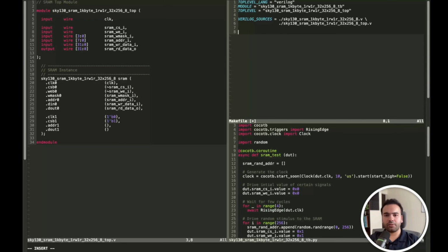And finally, we want to include the cocotb makefile. This can be done by using the include keyword here, and we need to find where those makefiles are present. This can be done by running the command cocotb-config --makefiles. This returns the path where the cocotb makefiles are present, and from that path we want to pick Makefile.sim, because that sets up the entire simulation flow for cocotb. So once we have all of this, now we are in a position to run this on our end.